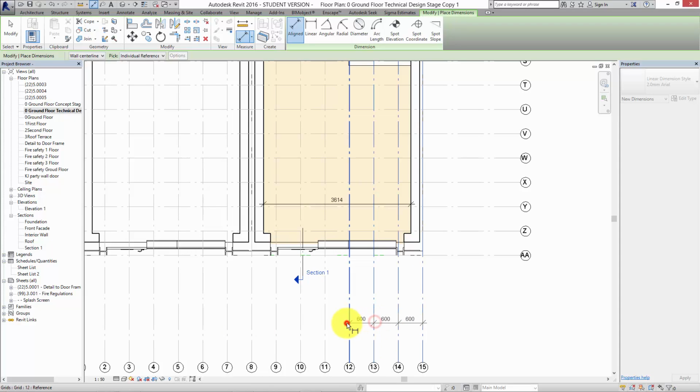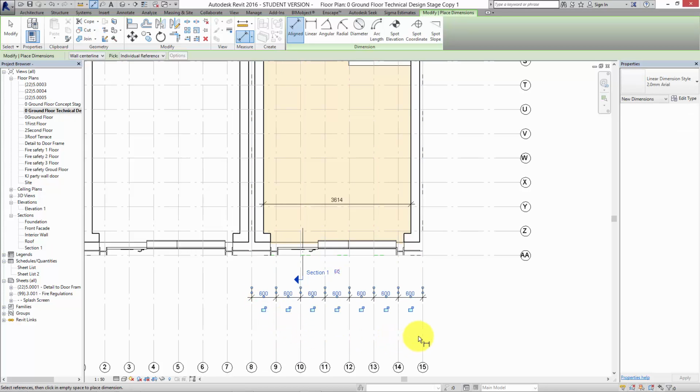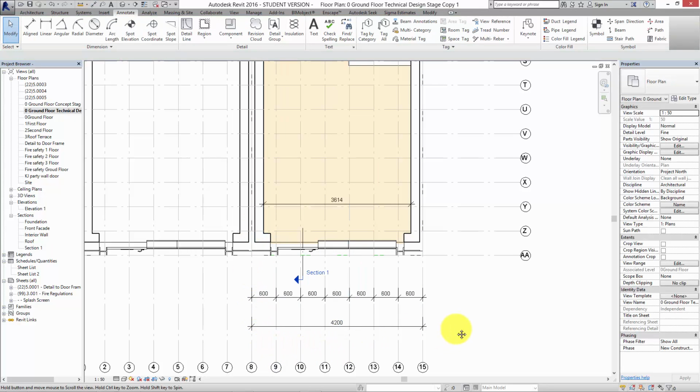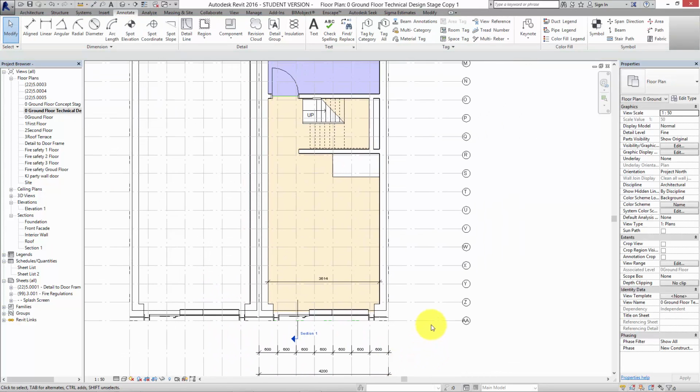And these grid lines are kind of excessive. You would never show grid lines every 600 millimeters. This is just for second semester. But there would be a grid line between the main structural elements like that. But you always have individual measurements, overall measurements, okay?